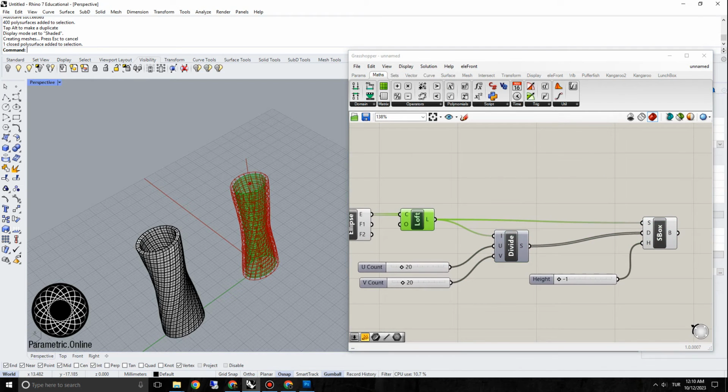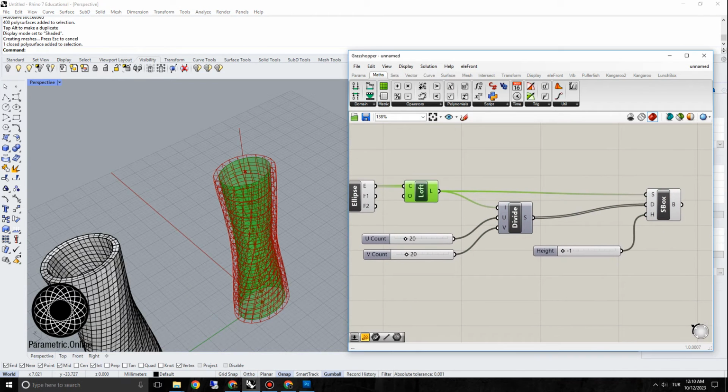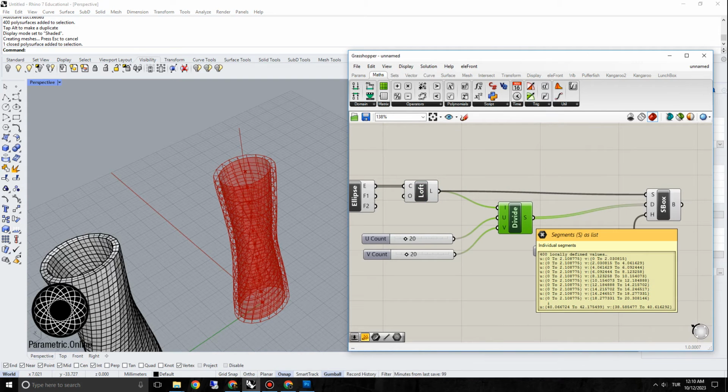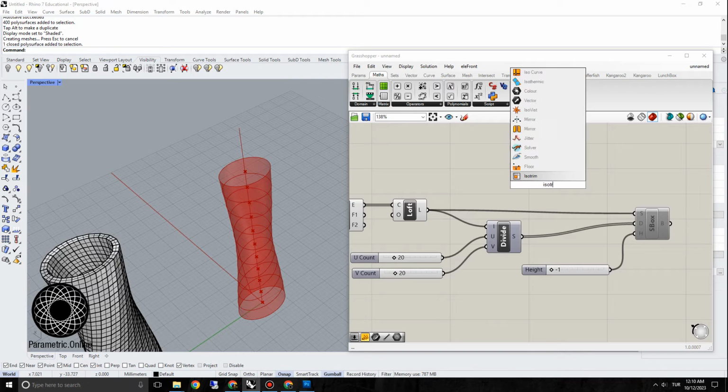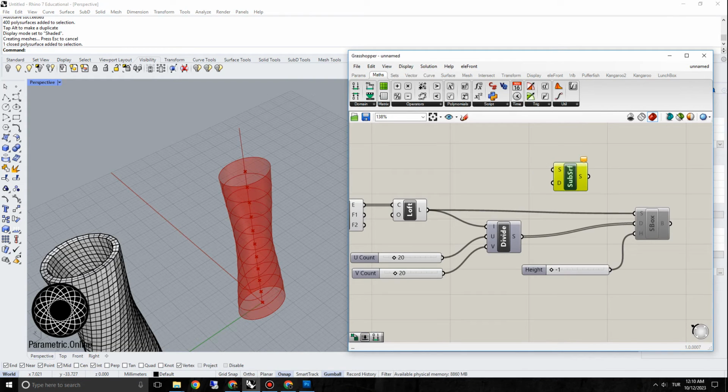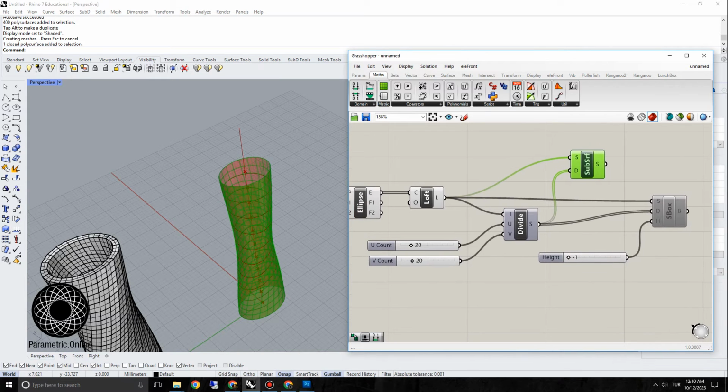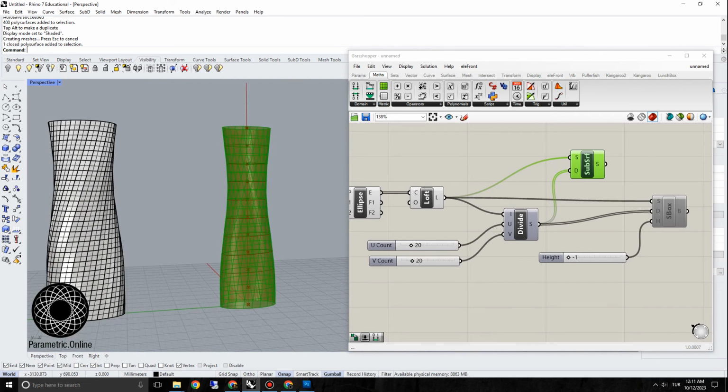I basically have a surface and I'm dividing it into panels. So we can also see these panels with isotrim. We're going to use these functions a bunch of times. So you can take the surface and the division. What isotrim and divide domain squared does is, the surface has a grid. We use u and v values to actually understand it.